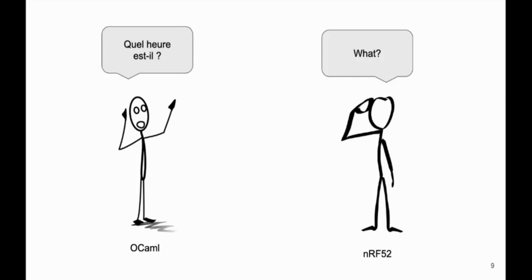Not only this, a second more difficult issue is that the board doesn't just start ready to run. There's an awful lot of initialization that needs to be done to get it into a state where it can run the runtime. For example, initializing the processor, registers, exception handlers, stacks, that sort of thing.